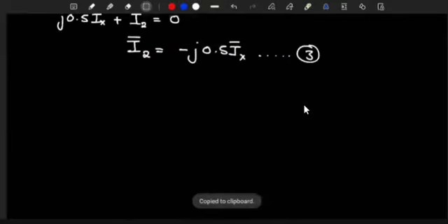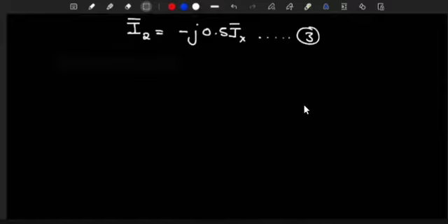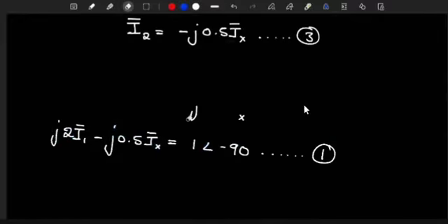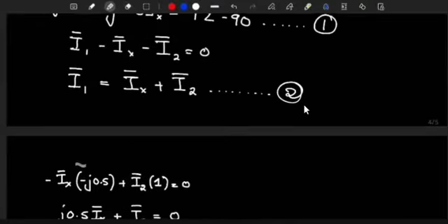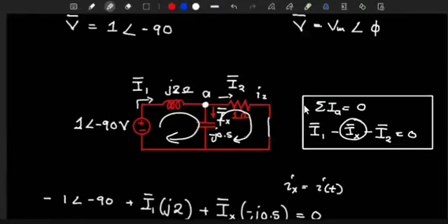Let's try substitution. How did you get the third equation? How did I get it? So this is where your previous question came in. I used the voltage law on this part. So I was looping this side. When looping this side, I said you come this way. Since you are going opposite to Ix, you get negative Ix there, times the impedance here.